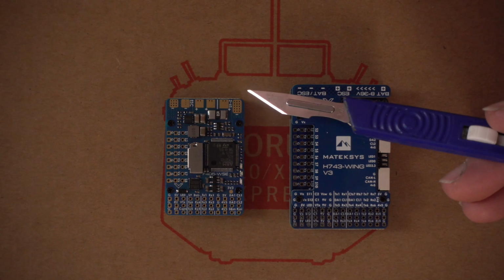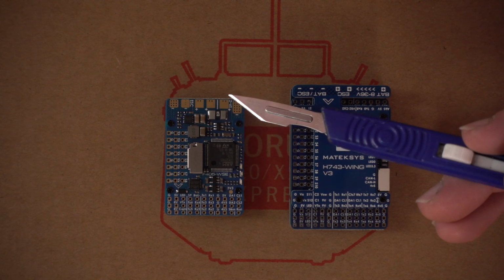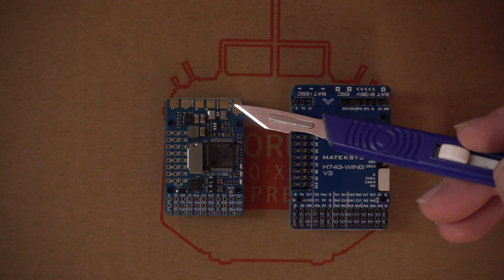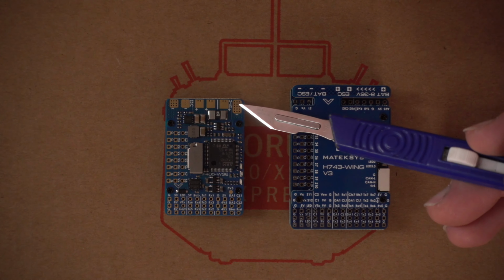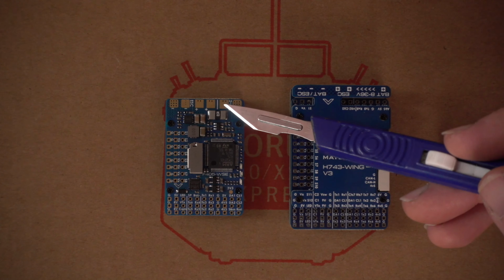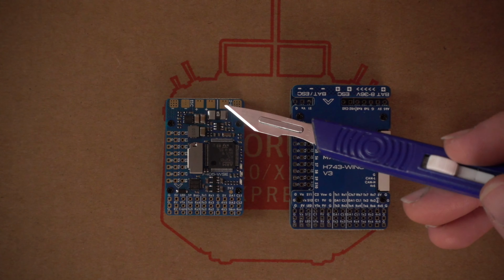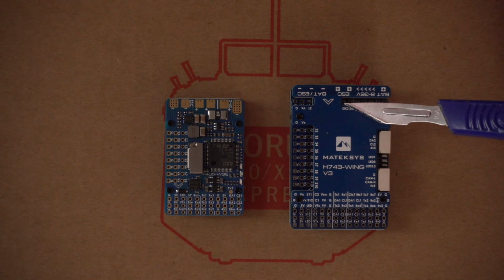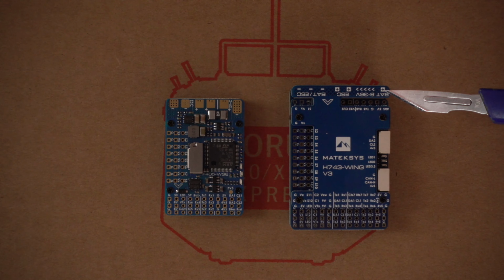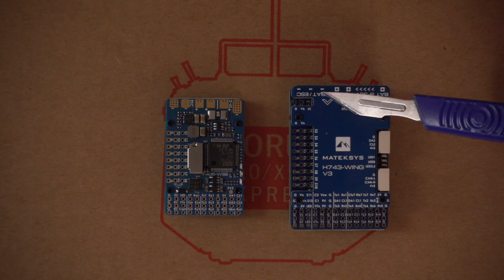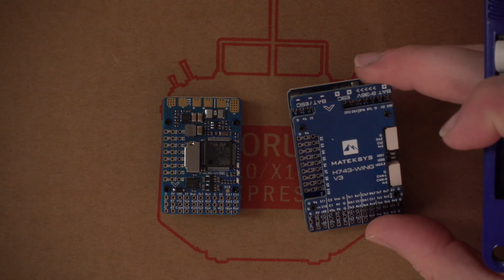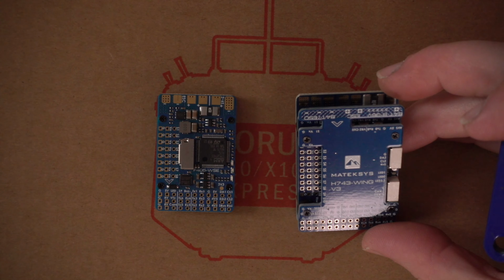so the first thing that we may need to know about is where we connect our main power. You'll see here that it says 2S to 6S with a plus and a negative. There are main battery power where it comes in straight from the battery. On this flight controller it's a little bit different. We have our battery positive here and our battery negative here. Obviously that is underneath. You can just see the pads there.